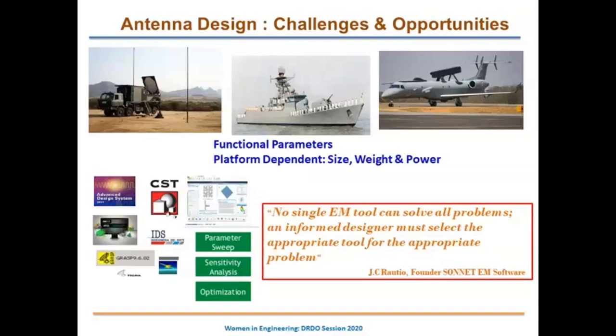But I just want to highlight this quote by the founder of Sonnet EM software. He mentioned that no single EM tool can solve all problems. An informed designer must select the appropriate tool for the appropriate problem. So you need to have a background of electromagnetic theory, because all these software packages work on different techniques. Some work on FEM, FDTD, PO. So you have to choose appropriately depending upon your requirement as well as the complexity of your problem.